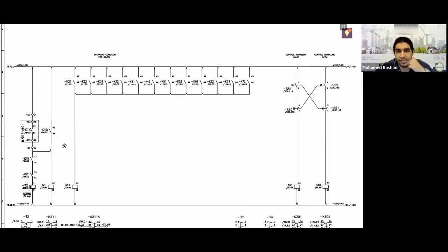Let's focus together. Now, suppose you gave the disconnector switch a command. The disconnector moves, it moves, it moves. It is supposed to cover its distance in about 3 to 5 seconds. All right? This disconnector is sitting for 10 seconds, 20 seconds, 30 seconds. Wow. How long is it supposed to take in the first place?